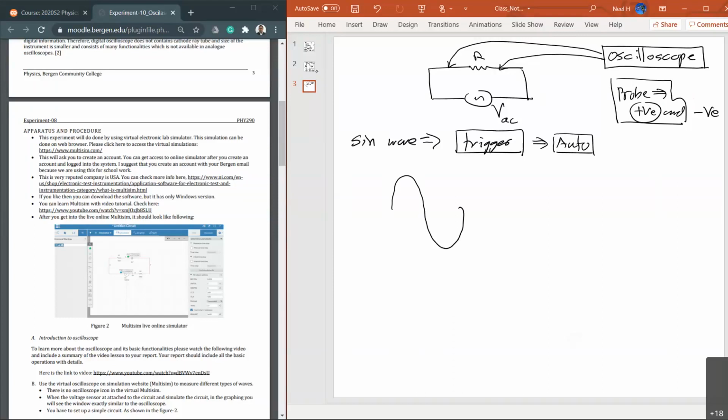So something like this kind of waveform you can observe on the screen. Make sense? So that's very important. Before you do anything, you always have to put it into automatic triggering. Because if you don't do that, you will see this waveform continuously moving along the x-axis in one direction and the other. Because of that, you can't do a measurement because it's always moving, right? You have to stabilize it first. That's one important thing you always have to do.